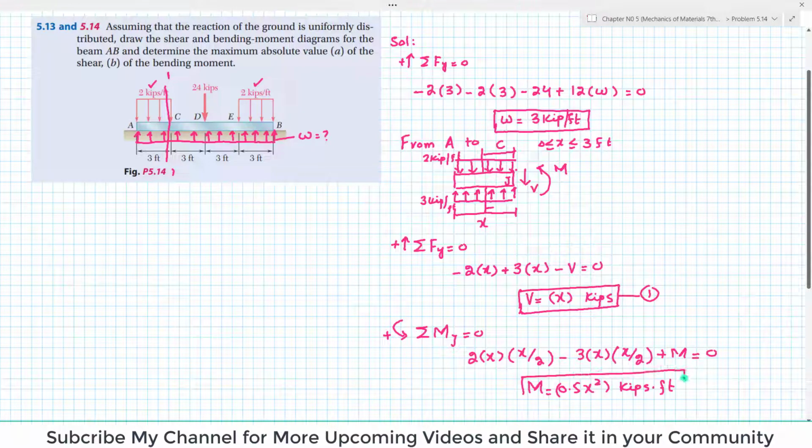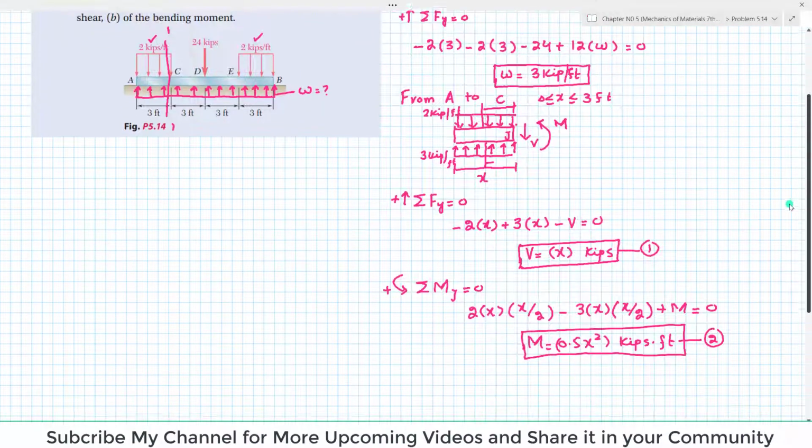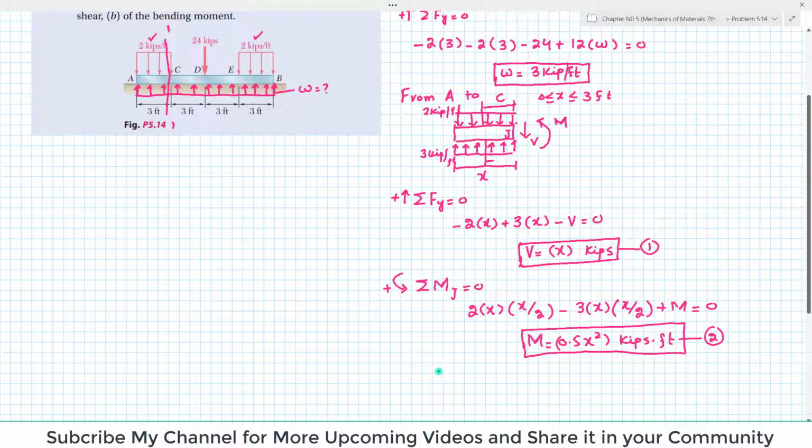So this is equation number 2. Now this equation 1 and 2 is valid for x greater than 0 and less than or equal to 3 feet. So let's put x equal to 0: the shear force will be 0 and the bending moment is equal to 0.